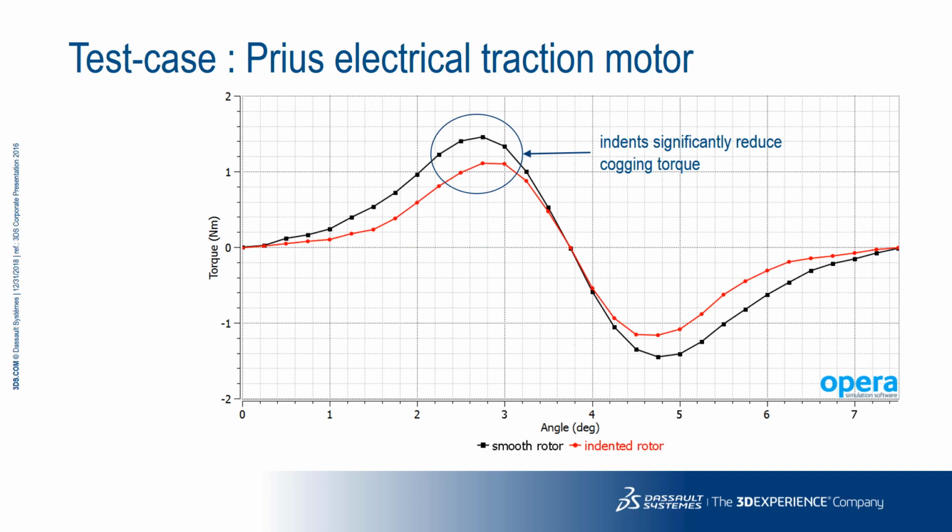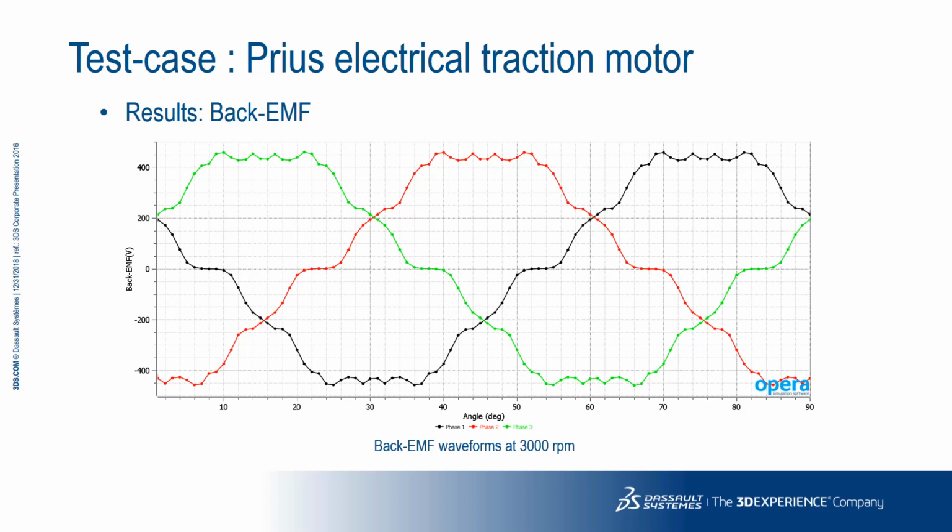We can now see the results obtained from the cogging torque analysis where the rotor was moved through 7.5 mechanical degrees. The effect that the customizations done to the rotor have on the machine performance can be easily seen. The peak cogging torque is reduced by around 20% and the overall shape of the curve is smoother. This will result in a more efficient use of the power available coming from a reduction in torque ripple and ultimately will result in less vibration and noise.